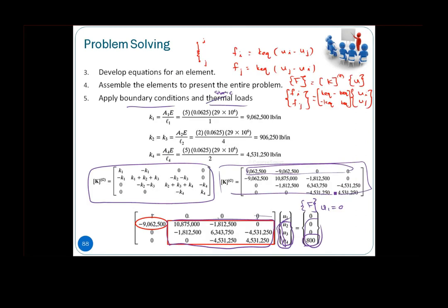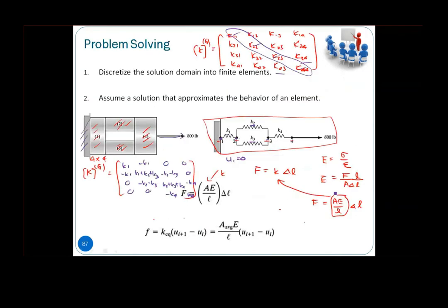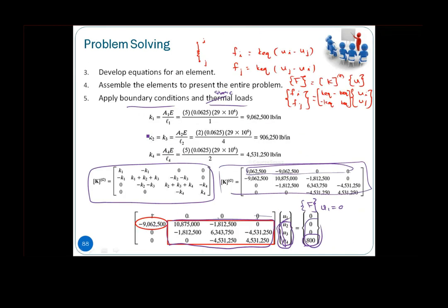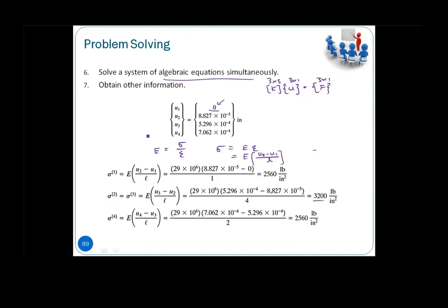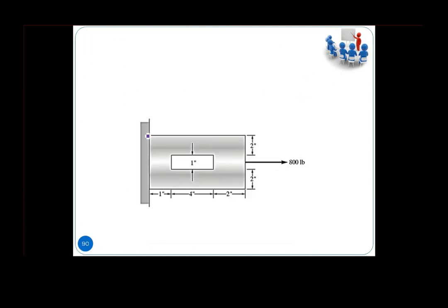Probably this is due to stress concentration here, because you have the discontinuity here, so you induce a higher stress in these particular regions, right? So that is some sort of analysis that you can calculate manually, right?